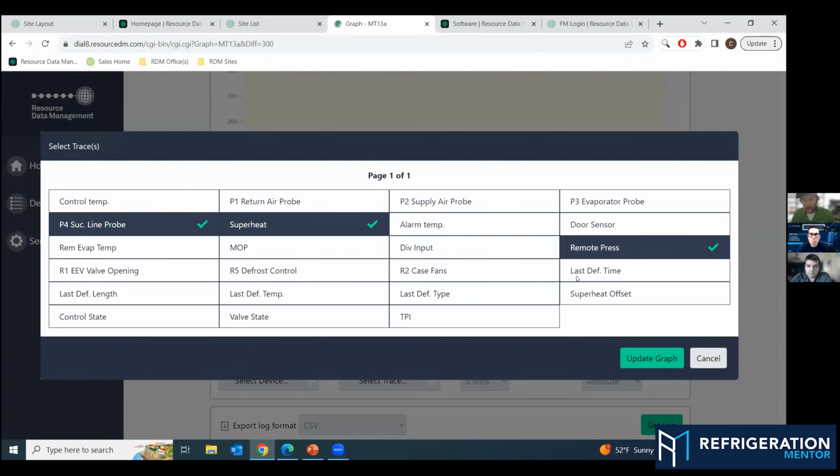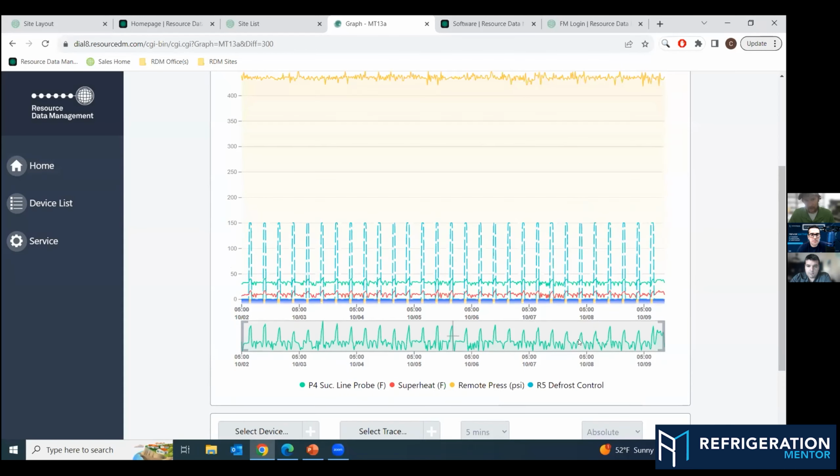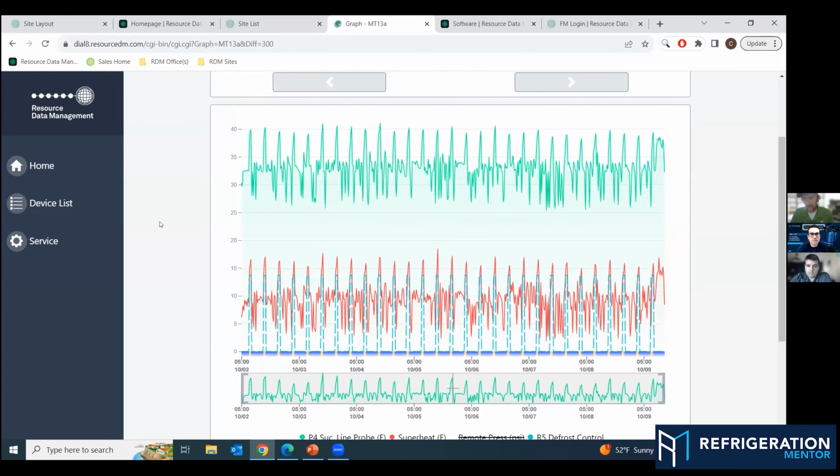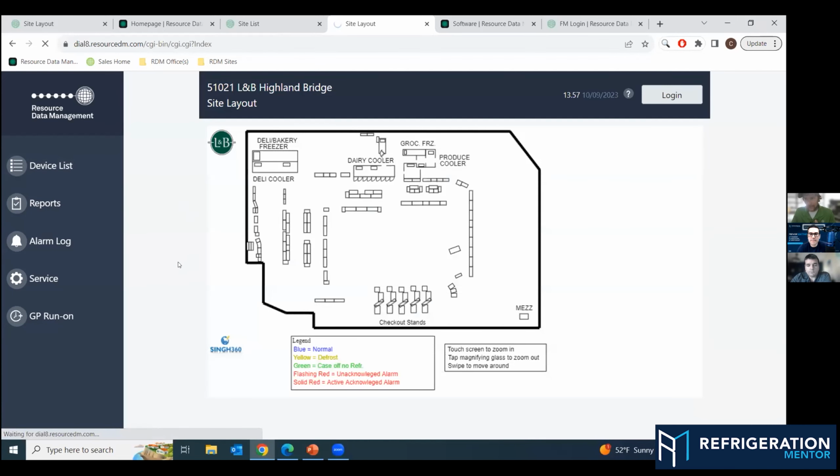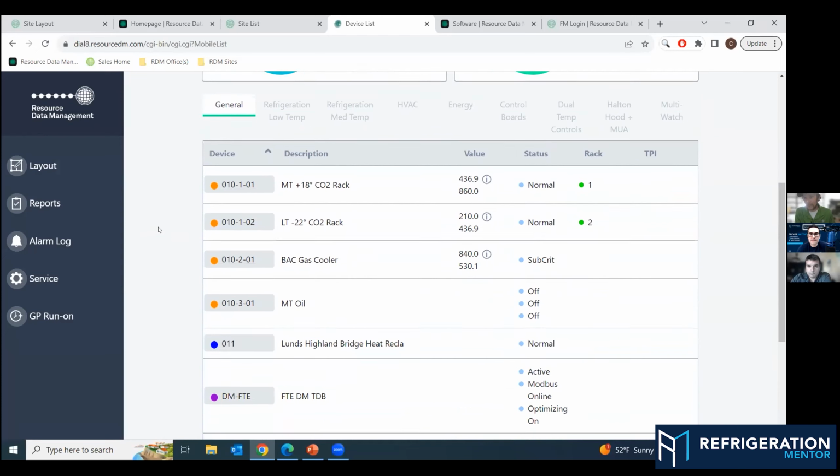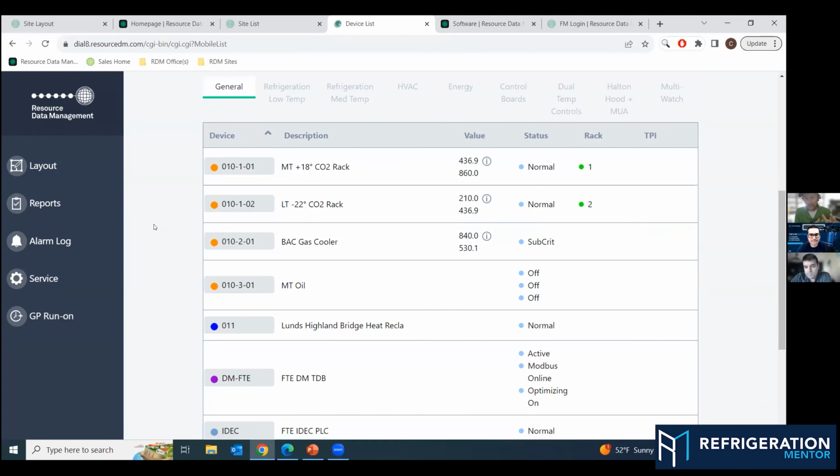But one thing I always reiterate to technicians I'm training: guys, just because the controller says that's what it is, that doesn't mean that's what it is. And this goes for any controller. I've done them all. I've set up a complete store in 2 weeks' time with Micro Thermal, setting TXVs. I would set a TXV and then the end case wouldn't be right. Just because you set the controller at 8-degree superheat doesn't mean it's 8-degree superheat. Just FYI, put a probe on there, and still do the normal techniques you would do at startup to verify.